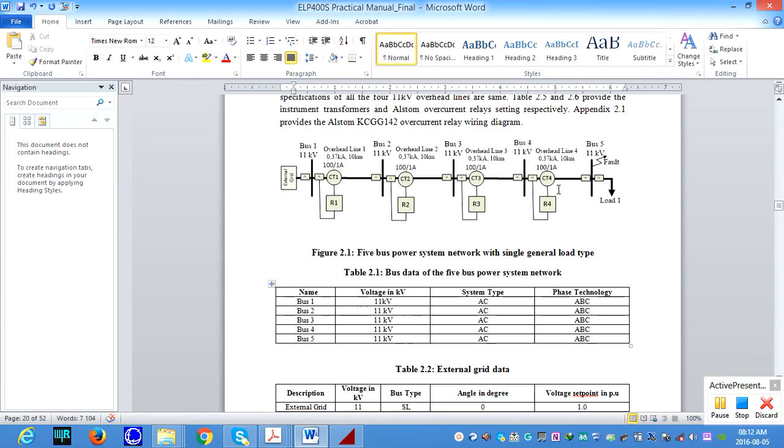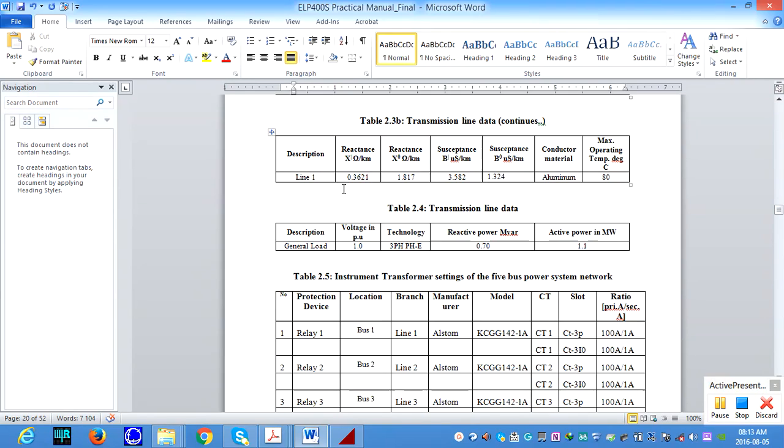For any specific reason, let us say a breaker failure or anything happens to this breaker, so it fails to trip within its time dial setting, then this relay will trip at the next highest time dial setting. The same thing follows: after this one, the next relay will trip, and after that one, the next will trip. So that is the principle we apply for the coordination time.